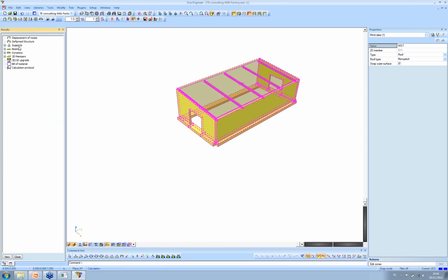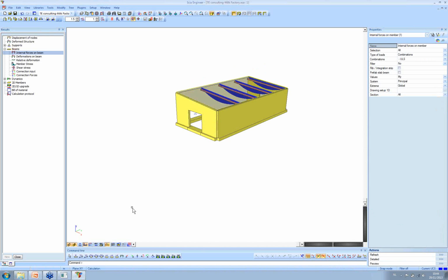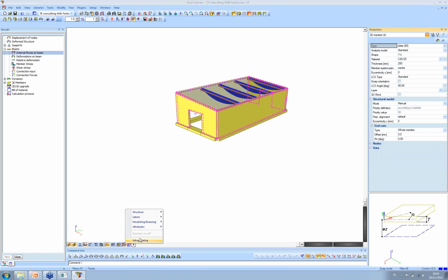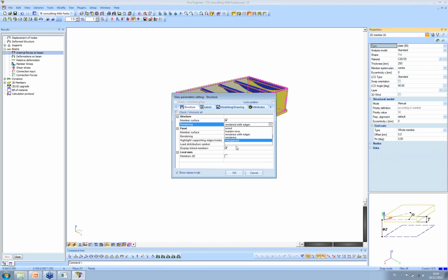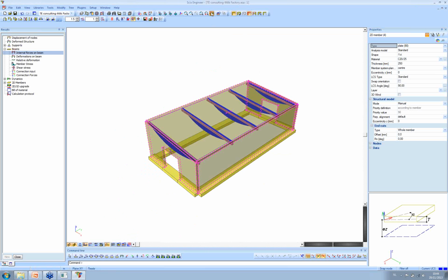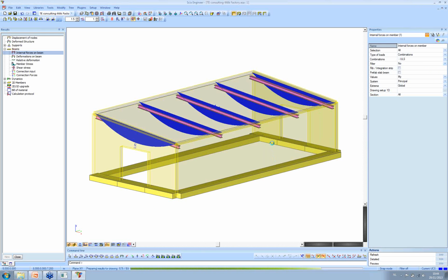And let's say that we are displaying the internal forces, the moments on the structure. Now we have something like this. I'm going to set the walls to transparent. Number, select, plate, select, and let's put them into transparent so that the image is a little bit nicer. Okay, so let's suppose that we are sending this image to our engineering report, live picture into the engineering report.